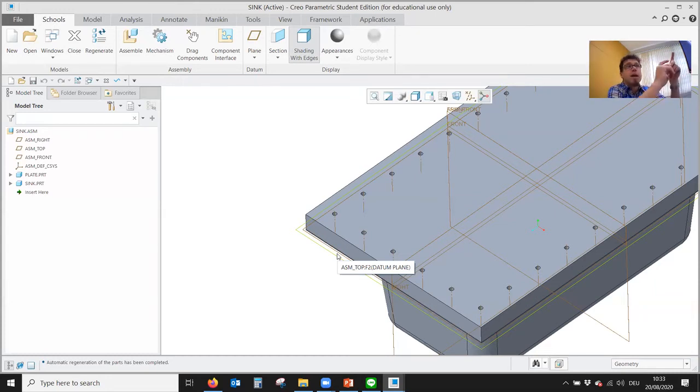So step one, they call that a mother part. Then get the book that gives me all the dimensions of all the sizes of screws and copy these dimensions into an Excel sheet. And then make SolidWorks open the Excel sheet and automatically make a new version of the part with the new dimensions from the Excel sheet, every size, M2, M4, M5, M6. And save that new file with a new name.